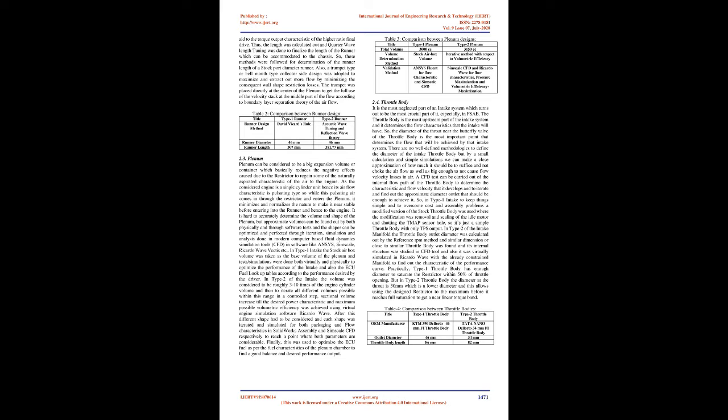From there the length of the runner was calculated, depending upon the RPM level at which the max torque peak is to be achieved. The events of open wheel racing are fully dynamics-based, hence it is required to get feedback from the driver about the track suitability. It was considered to be 7000 RPM for the stock max torque RPM for Type 1, so the calculation according to this methodology resulted in a certain length.